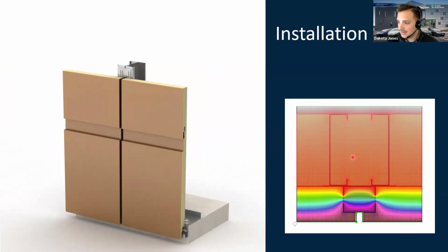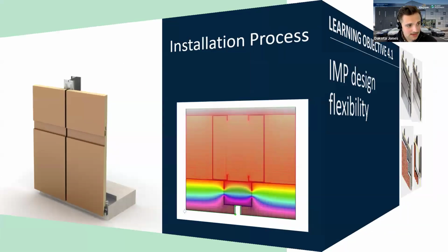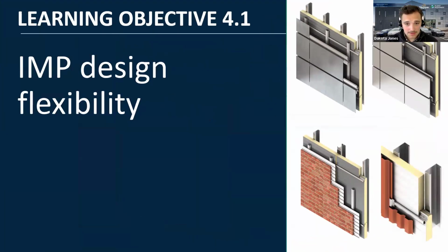This is a block spline detail. Essentially, it's a smaller IMP attached to that double stud system before any of the stuff goes on there, and then we notch out those IMPs for you, and then we have nice consistent thermal performance. Insulation on insulation contact, much, much more reliable than something like this. This will perform, it's just going to allow that to get cold, unfortunately. There's just no way around it. So keep that in mind. If you guys have questions about that install video, now would be the time to type them and we can get to them at the Q&A at the end.